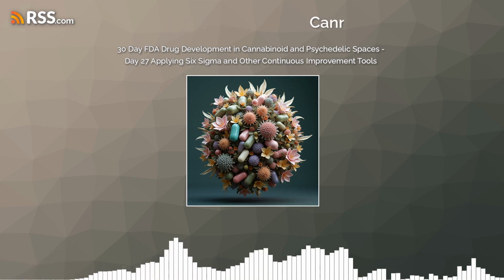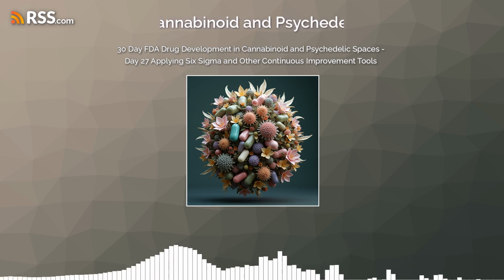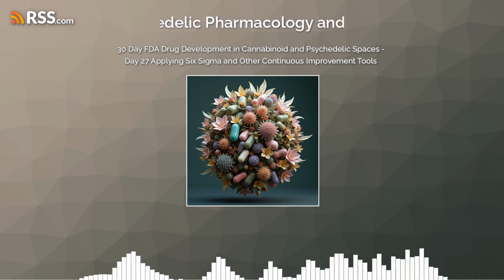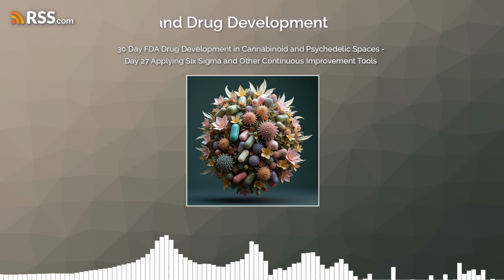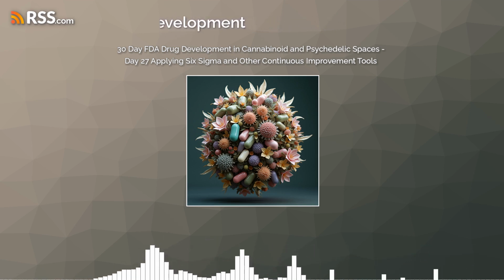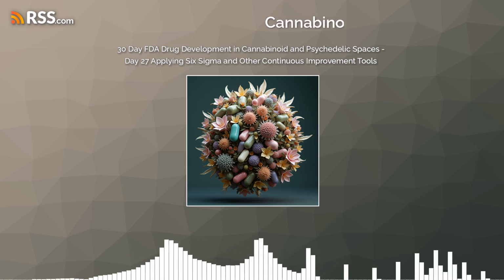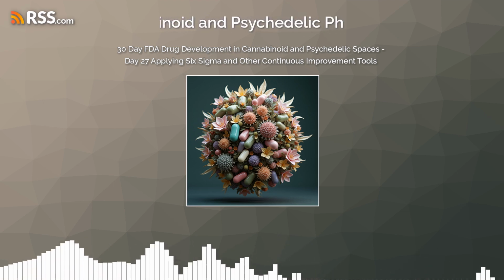Yeah, exactly. And it's a multifaceted approach. You need to be thinking about the starting materials that you use, the excipients. So those are the inactive ingredients that often go into formulations. You need to make sure that those aren't contaminated. And then really carefully control the conditions of every step in the process. So things like temperature, pH, even the purity of the water that you're using, all of these things can have an impact. So it's about attention to detail at every stage.